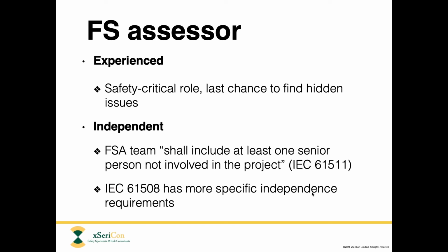Also, as I mentioned, there is an independence requirement, which in IEC 61511 simply says that there must be at least one senior person on the FSA team who's not otherwise involved in the project. IEC 61508, which is the overall standard covering all industries, has more specific tables detailing exactly how independent you have to be. For example, you have to come from a different team or a different department or a different office or even a different company. That is much more clearly defined in 61508 compared with 61511.